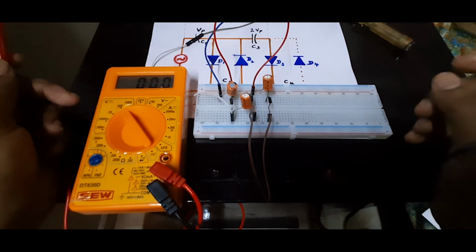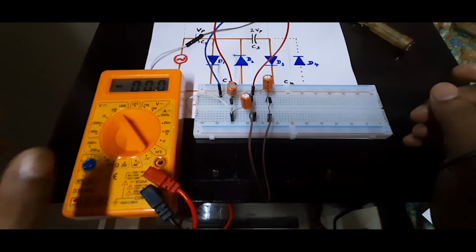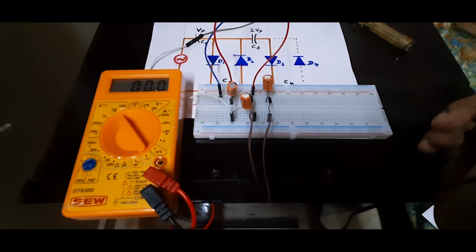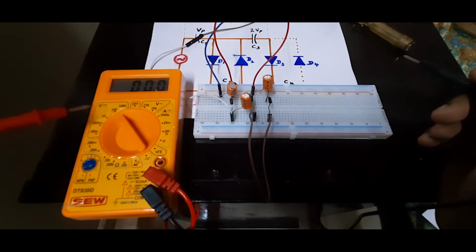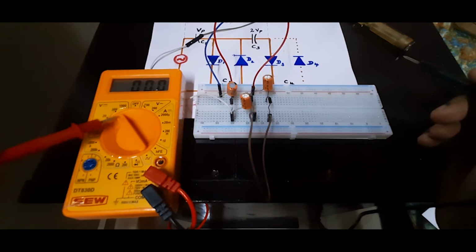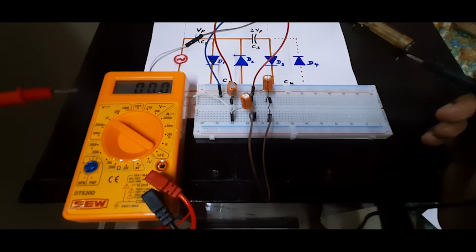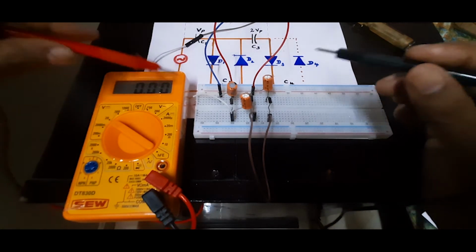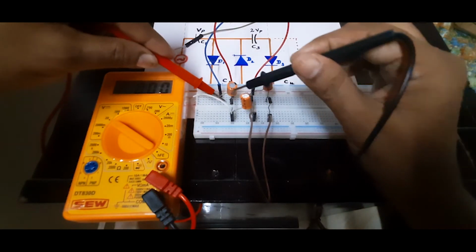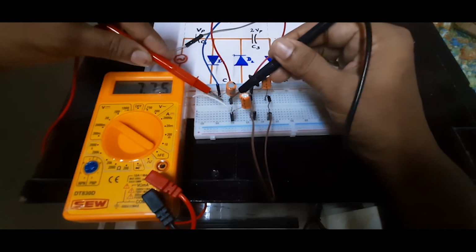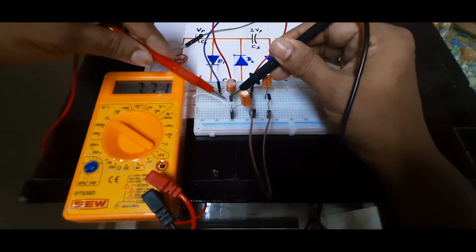Now, actually we should also measure the AC input voltage, that is the RMS value of the AC input voltage. These I am measuring as the DC voltage. Please see the knob here. I can put it in 20 if this is the DC voltage. I put it in the 20 range. So once again we can do a more accurate measurement if it is in the 20 range. So please note down if there is any correction.